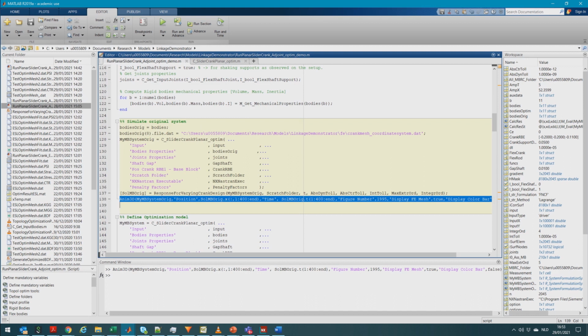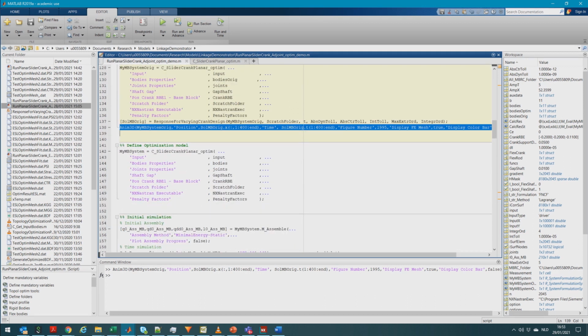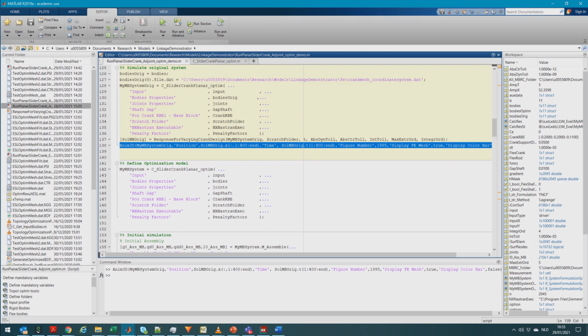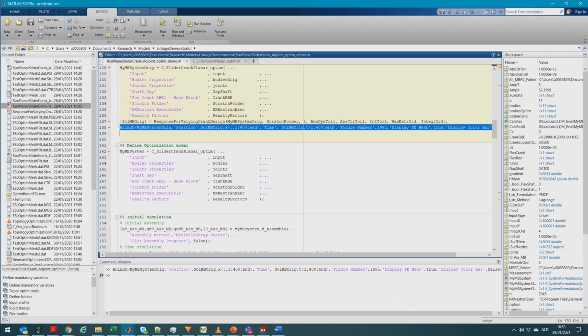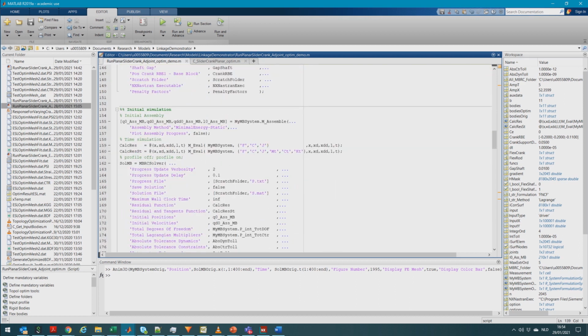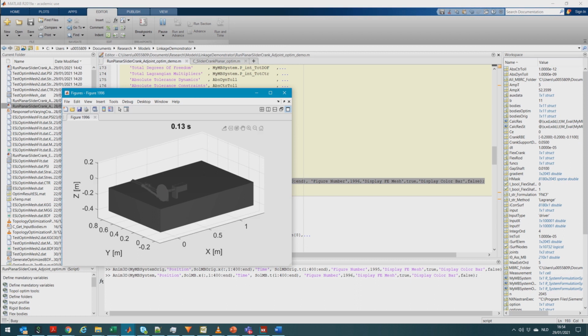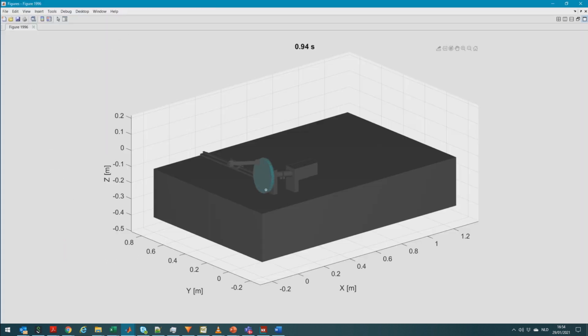So we define a new body, or a new system, where we input our new body, which we can use for the optimization, and that gives us a result that looks something like this initially. So we set up an entirely circular domain for the optimization. I can maybe quickly zoom in here. You see that there's a completely circular mesh here. So this is all the room that we might have available in order to do our design.